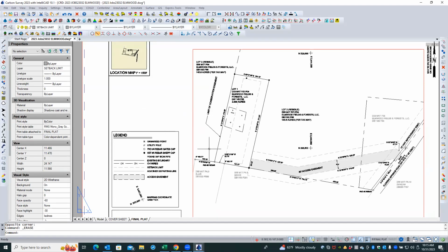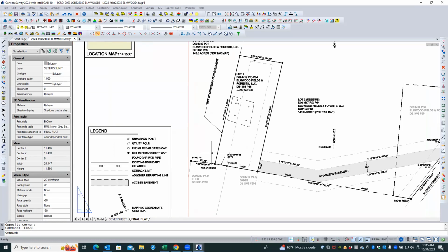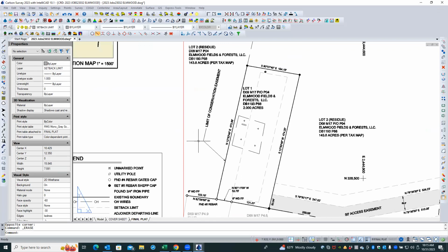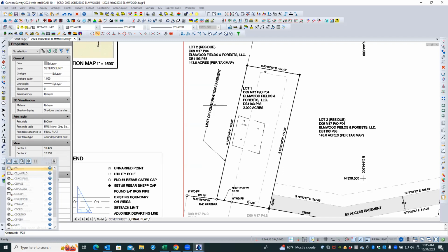So what we want to do is tell it temporarily, just for the duration of whatever we're working on, that this line is east, so that when we draw our leaders, they're going to be horizontal to that line. Okay, so they're going to be just like you saw us do before. And so then we come back out of that, and we won't have to change that rotation. So we're going to say UCS, that's user coordinate system.